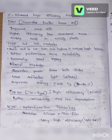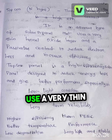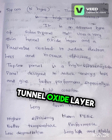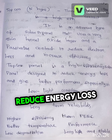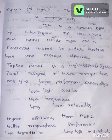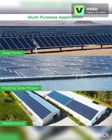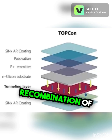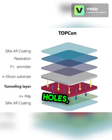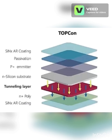Tunnel oxide passivated contact, TOPCon, is a high efficiency solar cell technology that uses a very thin tunnel oxide layer and passivated polysilicon layer to reduce energy loss inside the cell. This thin oxide layer allows electrons to tunnel through easily while blocking the recombination of electrons and holes, keeping more charge available for electricity generation.